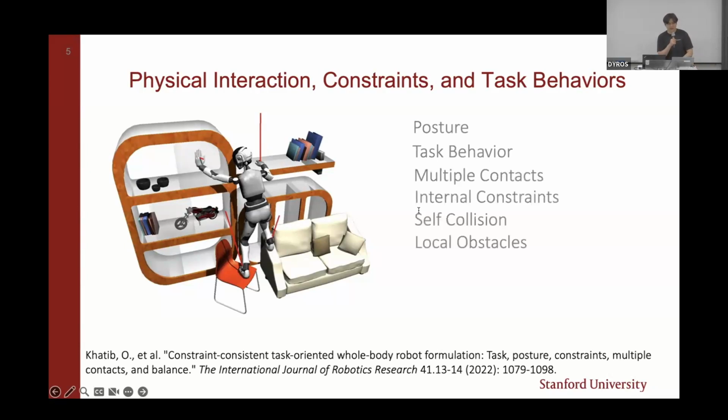So the framework enables strict hierarchical dynamically decoupled multitask control, where controllers for each task listed are executed in parallel. And the control input to the robot is the total control torques from all tasks, where task hierarchy is enforced using task consistency and dynamically consistent null space projectors. So altogether, the framework provides a very powerful methodology for controlling high degrees of freedom robots. This is the foundation for this existing work that I'm presenting.